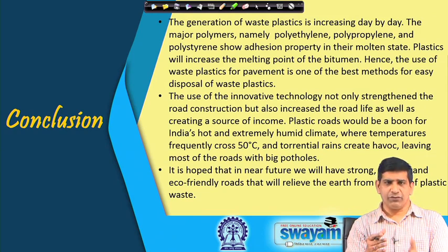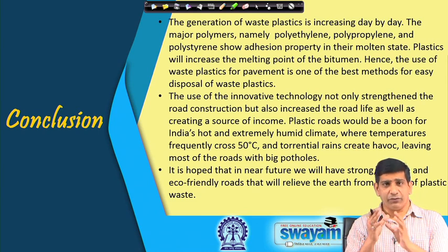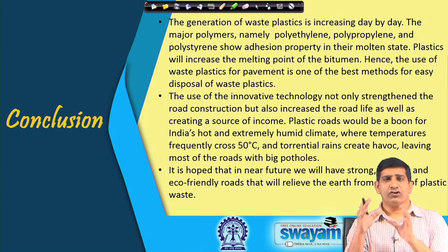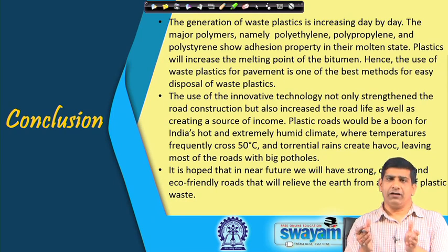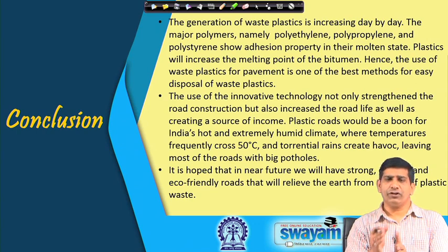For a waste to energy incineration plant, we can use mixed plastic together along with other waste streams as well. Plastic has a good calorific value, so we can use it in a waste to energy plant, but we have to do it at a pretty high temperature to make sure that no dioxin, furan, and other contaminants are formed. Even after doing it at a high temperature, we need to have a proper air pollution control system. So, that was the waste to energy part.